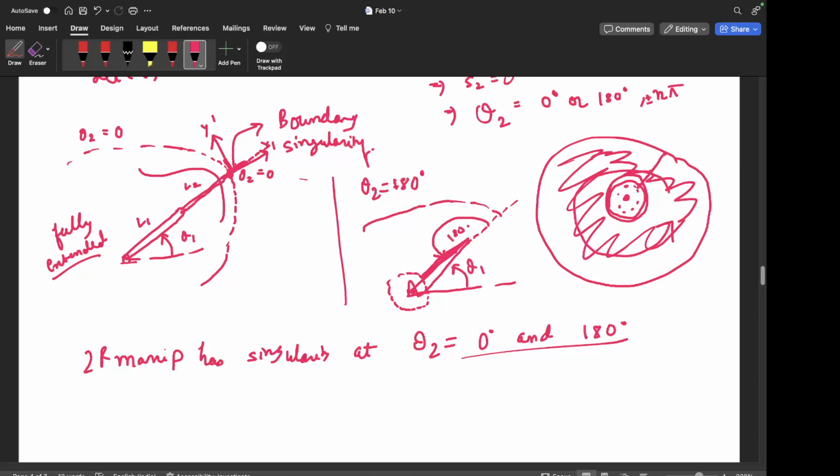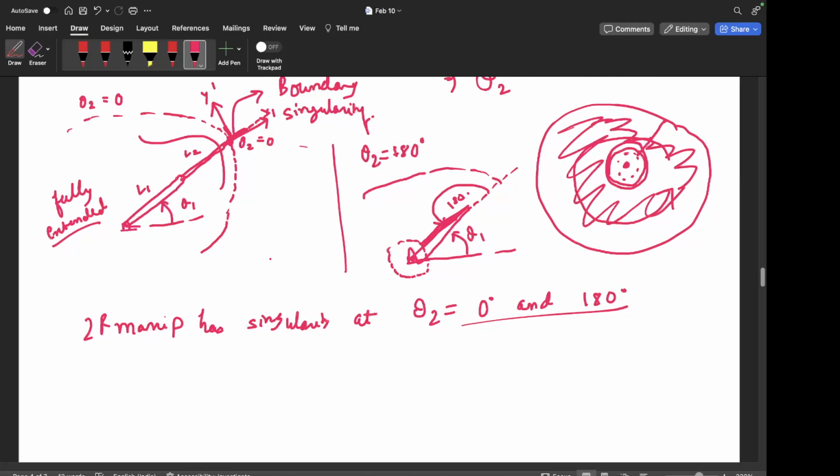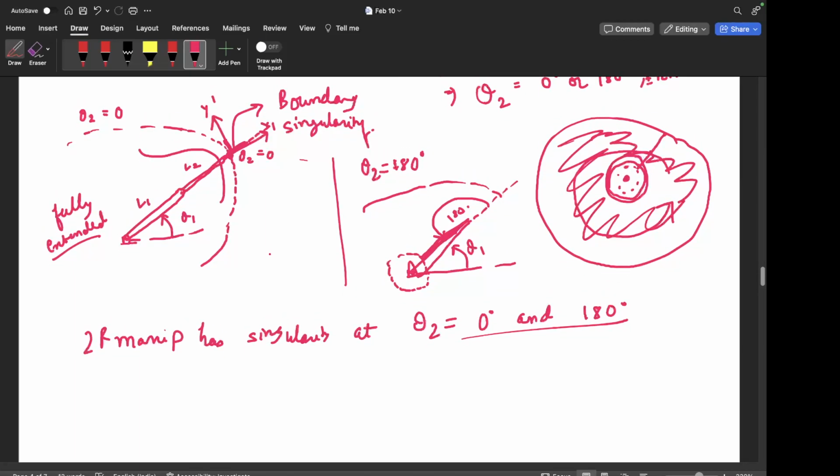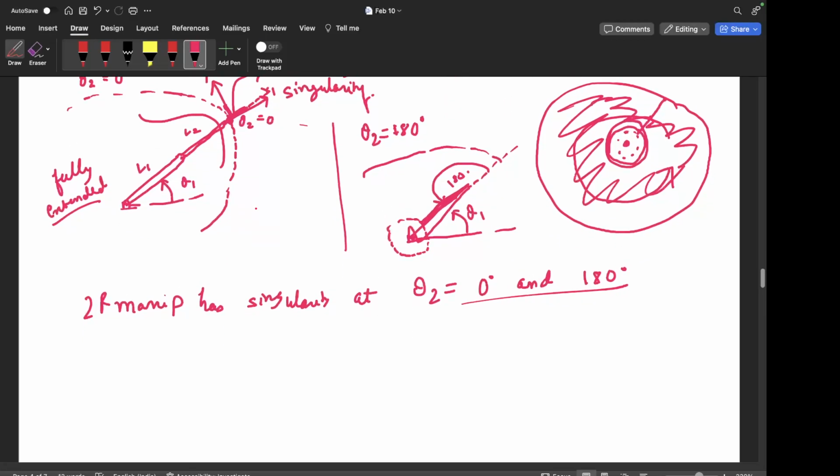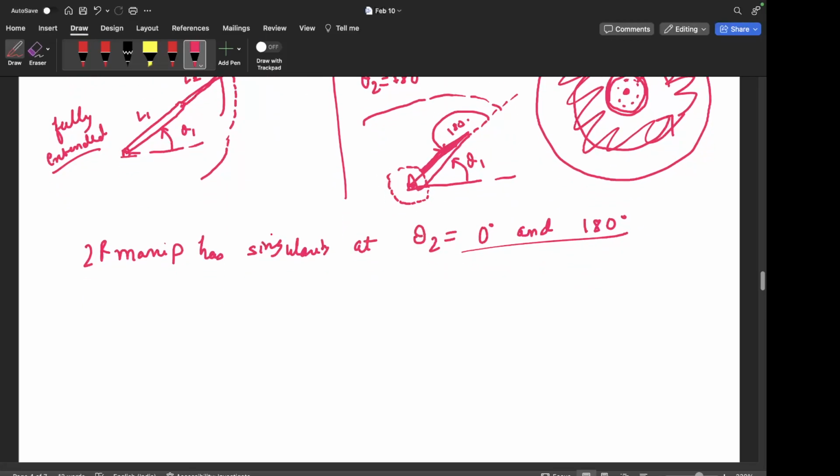And as I mentioned, the velocities would rise very rapidly. So again, the arms would get locked out, and basically some bad things can happen at those points. So for practical implementation, you would like to do this analysis first and keep your trajectories well inside the workspace. Okay.